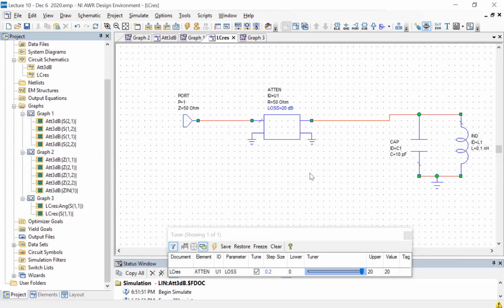If you use the same path, which is exactly the situation I have drawn here, you will not learn anything about the device, because the signal coming back will experience the same attenuation. And in a cryogenic environment, you need a minimum of 60 dB of attenuation to protect your device from the room temperature noise. So you will not see anything, because this attenuator will completely mask the signal.